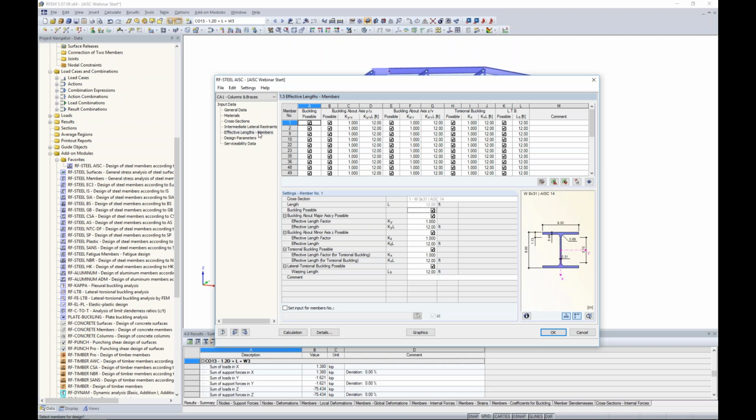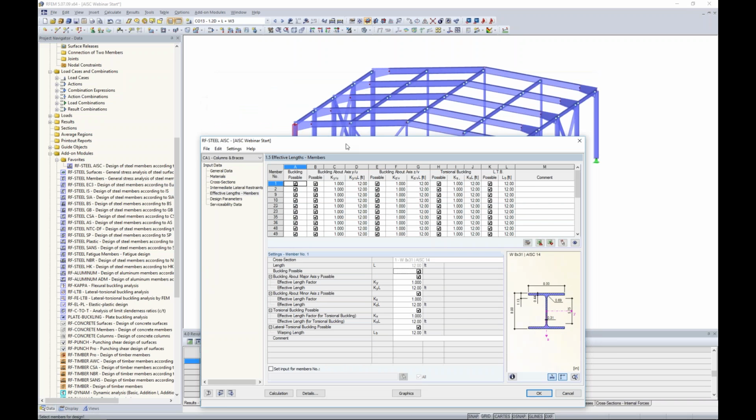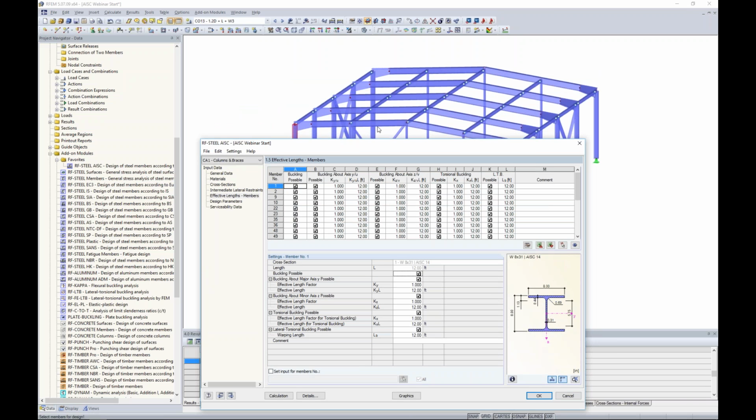And I can't stress enough how important unbraced lengths are. As a software program, the program is only smart enough to know the unbraced lengths as you've entered them into the program. Meaning you can see right now our unbraced lengths, which would be this column, we have a few columns here: buckling about the strong axis, buckling about our weak axis, torsional buckling, and lateral torsional buckling. We have the column here for our K values and our K times our L.